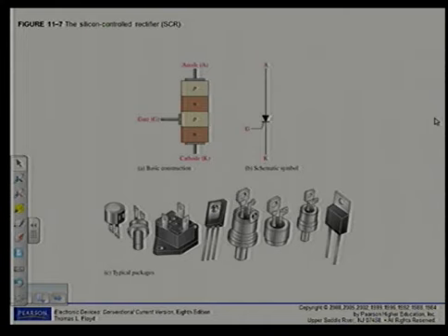In the on state, the SCR acts ideally as a short from anode to cathode. Actually, there's a small on or forward resistance, basically the same as we've discussed with the diode as well in Electronics 1. The LASCR operates as an SCR, except that it is triggered by light, but I will show it to you when we get there.